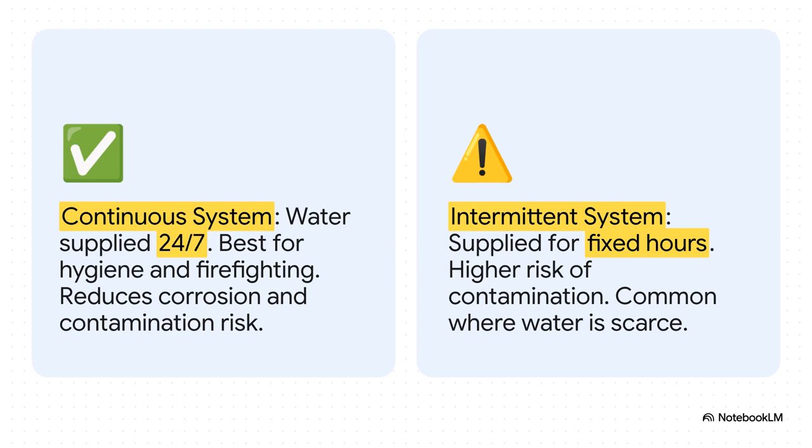Why? Because when the pipes are empty, they can actually act like a straw and suck in contaminated groundwater from any little crack or bad joint. That's a massive public health risk you just don't get with a system that's always full and pressurized.